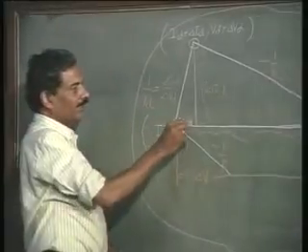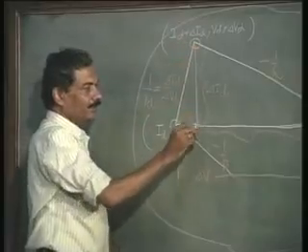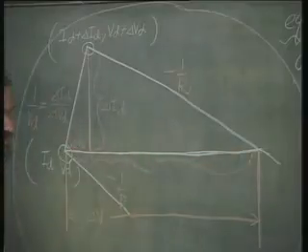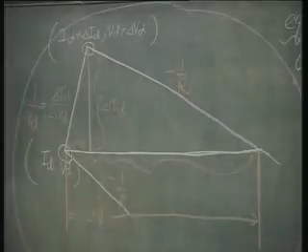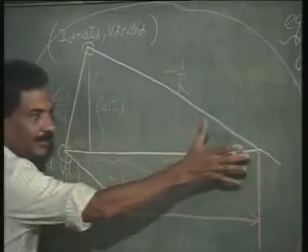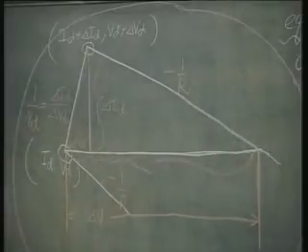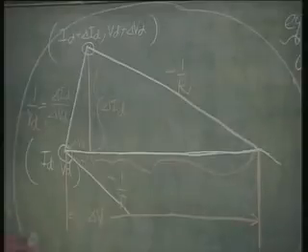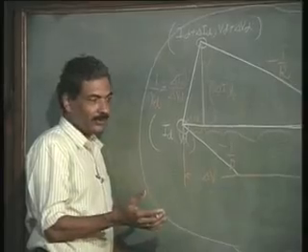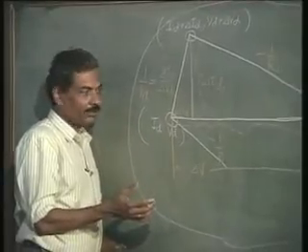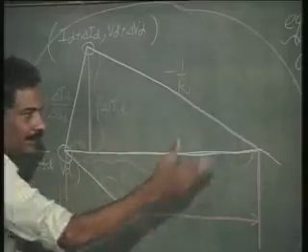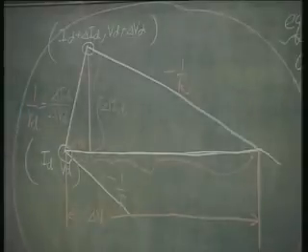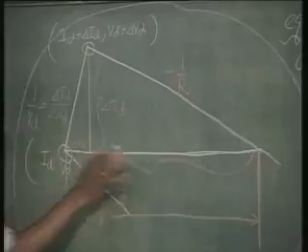So, this is delta Vd, this is delta Id, this is the delta voltage across the resistance, and this is the total voltage across the diode. And we have seen that delta V is very nearly the delta V across the resistance, and therefore, the change in current is simply delta V divided by R. So, if it has changed by 60 millivolts and R is 1 kilo ohms, then this change in voltage is very nearly equal to 60 millivolts, because this is very small compared to this.